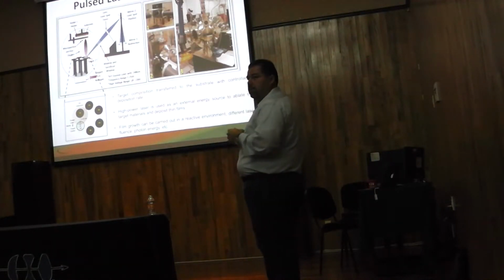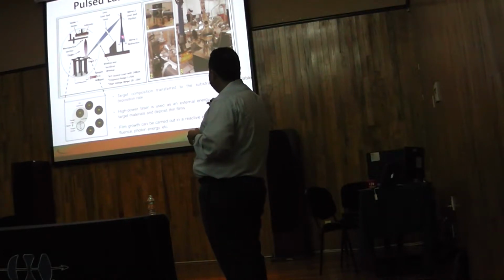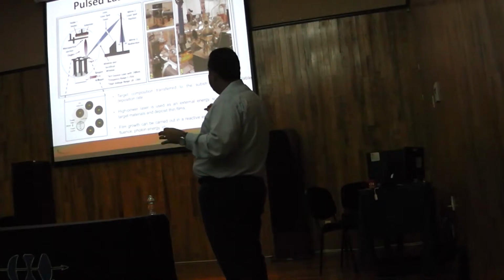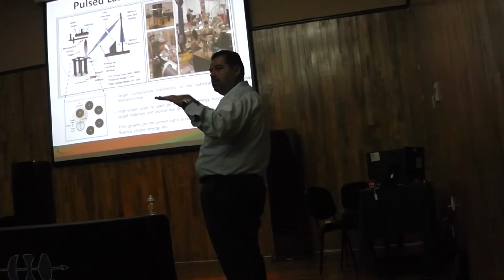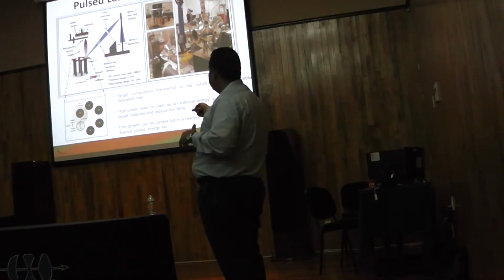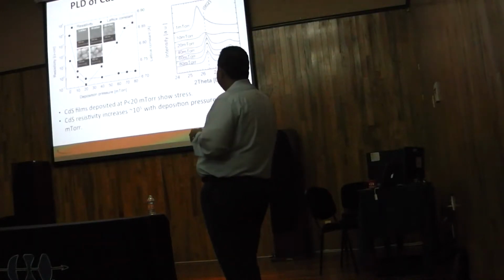So let's move on to pulsed laser deposition, and I won't even attempt to explain it here, in a room full of experts on optics. Basically, we have a laser and we have 5 or 6 different targets. We direct the laser to the target, which ablates the target and evaporates it onto the substrate. We can do a co-deposition of up to 6 different targets, which is great. That way we have target A, target B, and we can dope material A with whatever I have in target B. So it's great for materials screening.